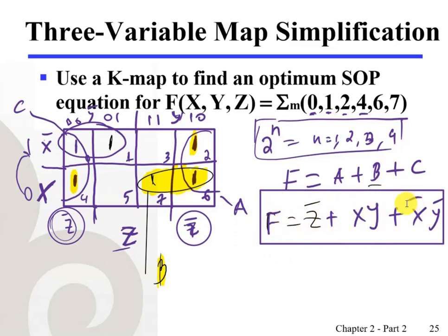So using the Karnaugh map tool, we derived the following optimum sum of products. Okay, optimum sum of products term by simply grouping. Our goal here, when we use Karnaugh map, is to find the largest grouping of ones. Here, largest was 4, right? If we maximize the grouping, then we minimize the literals. The group of 4 ones resulted in 1 literal, and then 2 groups of 2 ones resulted in 2 literals, right? So here, why we care about K-map. K-map gives us the near optimum solution for sum of products by just using this grouping tool.